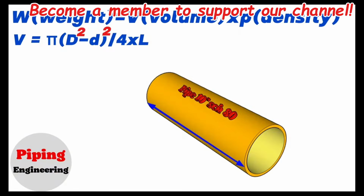We will look at the row showing nominal pipe size 10-inch. The outside diameter of the 10-inch pipe is shown as approximately 273 mm and the wall thickness for schedule 80 is shown as 15.09 mm. Now we can calculate the inside diameter of this 10-inch pipe.